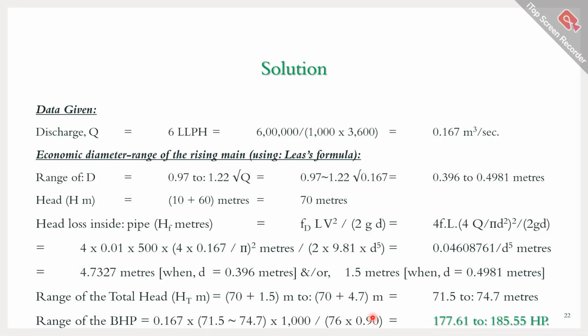Now that gives you the watt. What happens in this case? Here you have to convert that calculated watt into brake horsepower. So that I have earlier stated in the hint, one brake horsepower gives you 746 watt. So 746 or 750 comes in the denominator. So if you divide that thing with the G that is present at the numerator, G means 9.81.